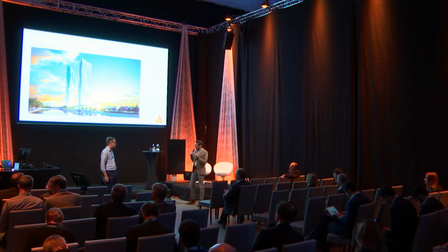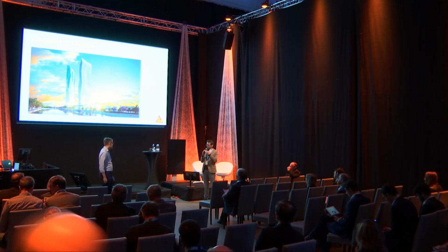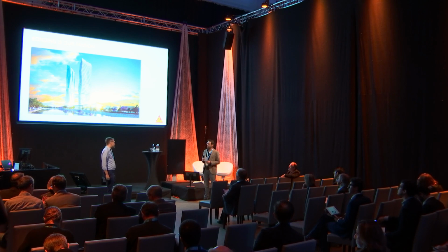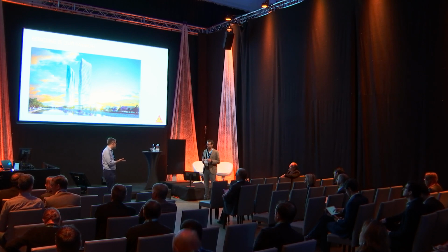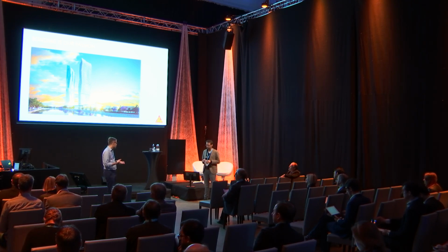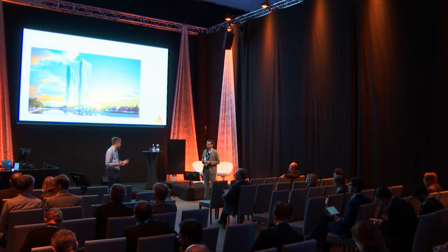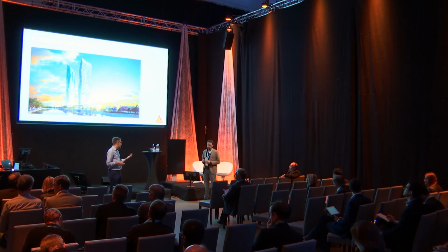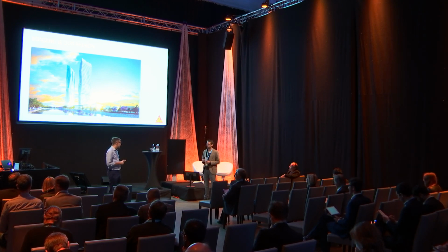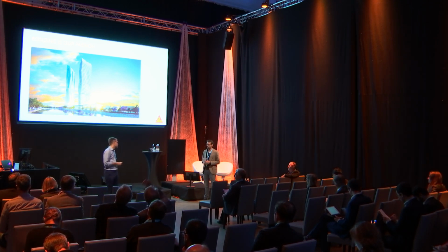But I also like the idea of the adaptive frame. But what about the position at the edge? For the edge, at the end of the day, there are possibilities to create a certain freedom inside the system. With an adaptive frame, you do not have unlimited freedom, that's for sure, because somehow you have to connect both frames with each other. And then, as you mentioned, on the corners, you could end up in problems. But the idea with an adaptive frame is not mainly to avoid any kind of displacement. It's more about reducing displacement in the structural joint.